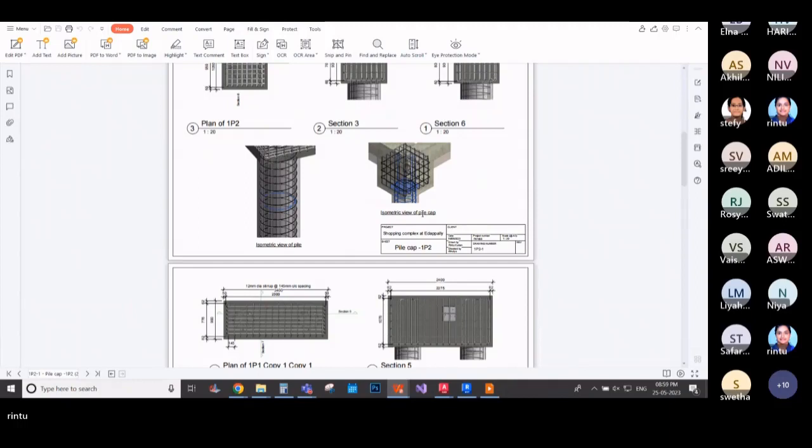Okay, you'll know just the size of the requirement for a building. You know the size of the building. You start designing it. You start designing the reinforcement. Then you have to implement it. So for implementation, you'll have to think what is the spacing that has to be provided so that the concrete can be poured without giving much pressure or much vibrations. What is the best spacing? What is the best shape to be provided so that it can be easily bent, cut, and placed in position? So all these are to be decided by you. And I'm sure you can't do it in one day. You will have to keep practicing so that you are getting better day by day.